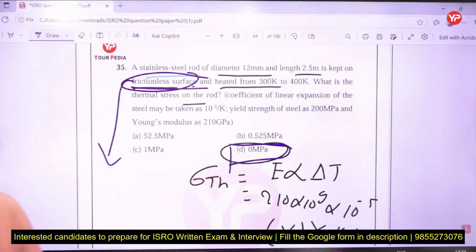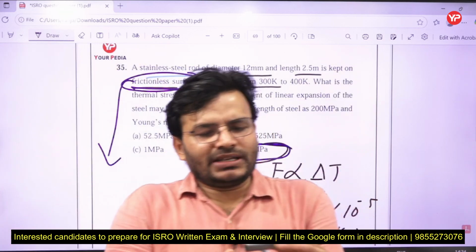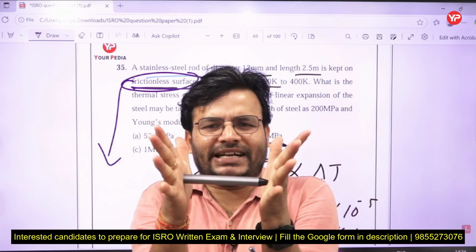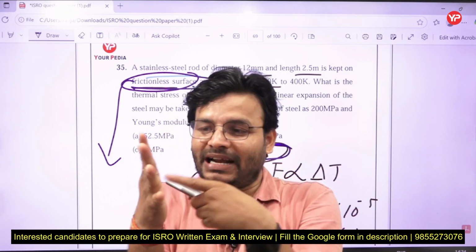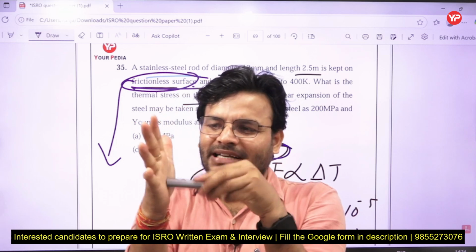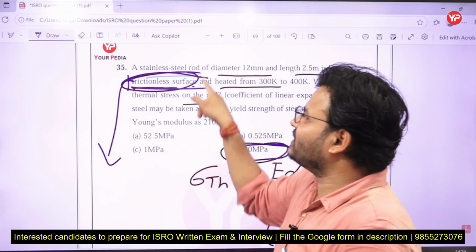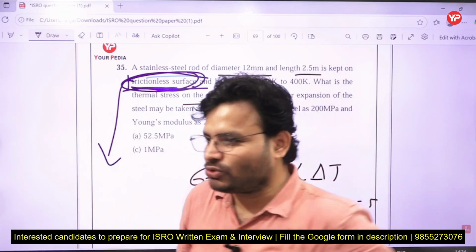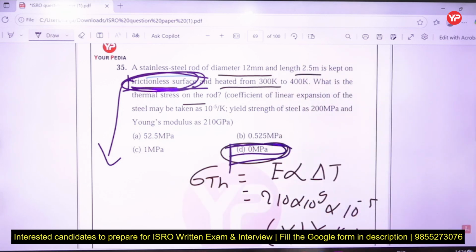My dear friends, you can ask, sir, how can we say that? Suppose you are going to heat them, and there is a restriction. If there is a restriction, will friction come? Yes, sir, friction will come at the interface of two surfaces. If I am going to heat them, then at the interface of two surfaces, friction will come. But the question says it is a frictionless surface. That means nothing is there. It is free to move. That's why, my dear friends, it is the case of free expansion, and your answer will be D for Delhi. 0 megapascal is the right answer.